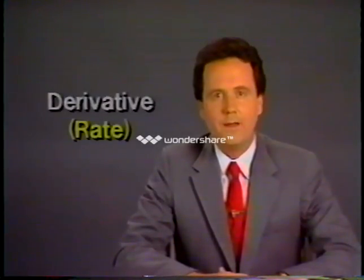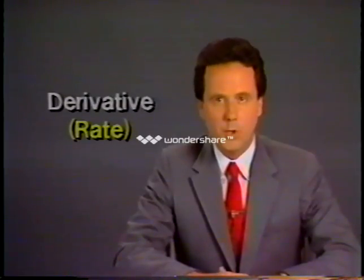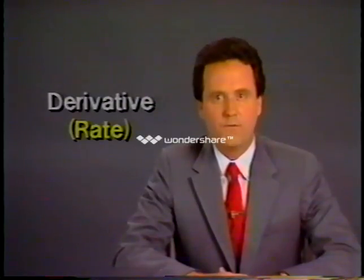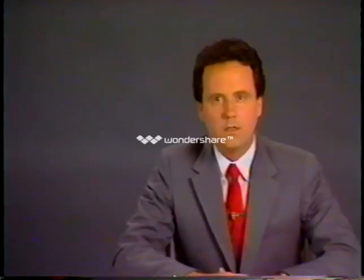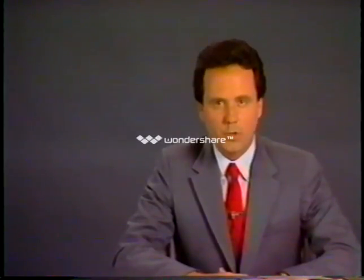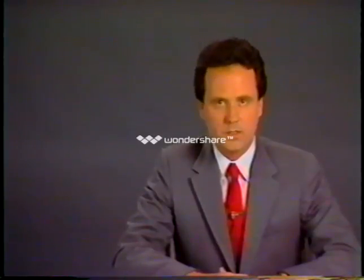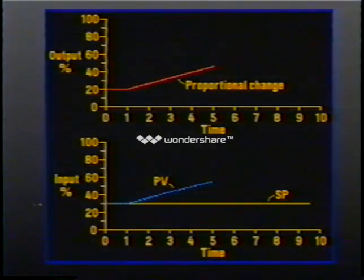The third mode of a PID controller is the derivative, or rate mode. The controller output from the rate mode is a function of the speed of change of the error. Once more, we go to an open loop so that we can better observe the controller output response. Here, we have an error that is ramping upward.